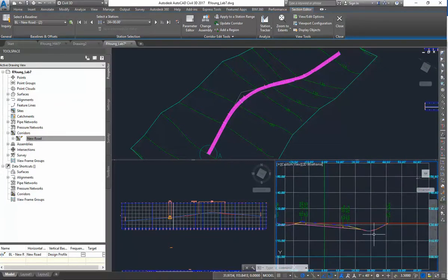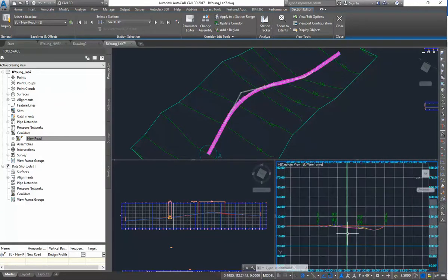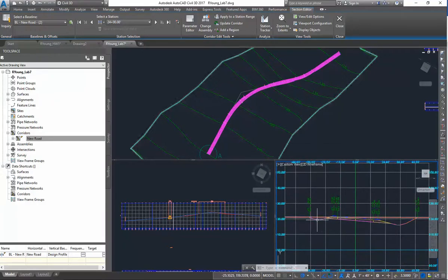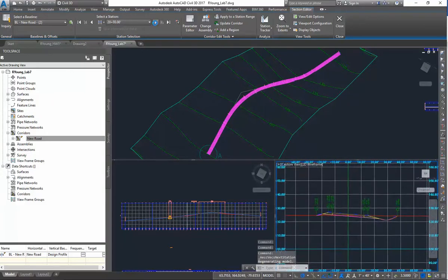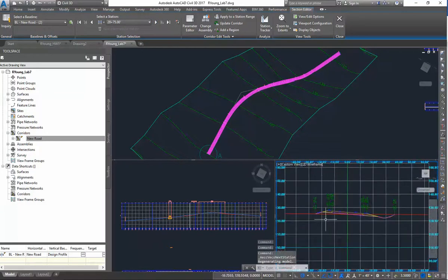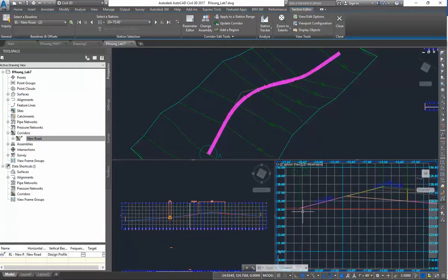If I look at the other side, I have the same thing. It's creating that ditch. So that's what happens when I'm in cut. So it creates those drainage channels. And then I'm just going to kind of keep going. And so now I'm looking at a point up here. Looks like I'm at station 28 plus 75. At this point, I'm in a fill section, so it's just going to find that daylight line.